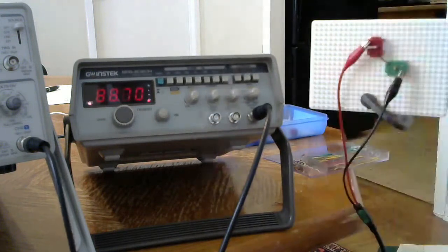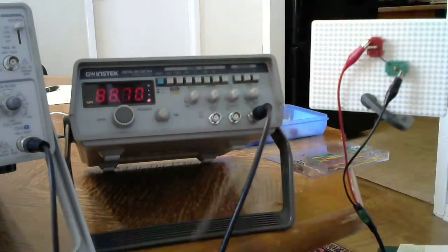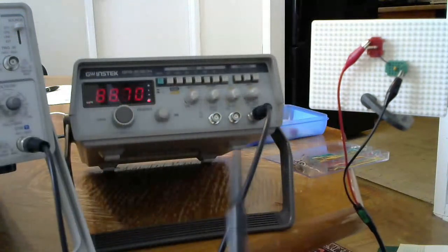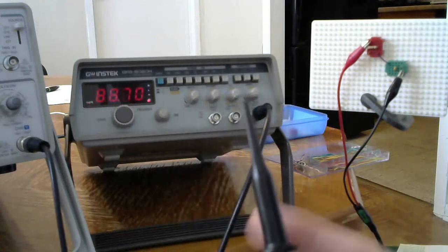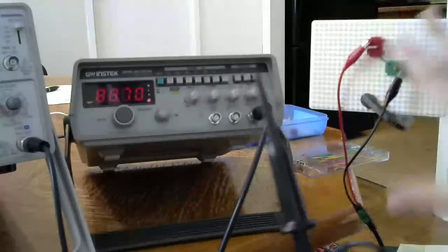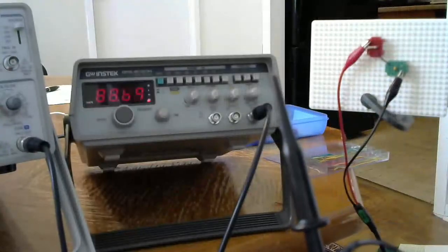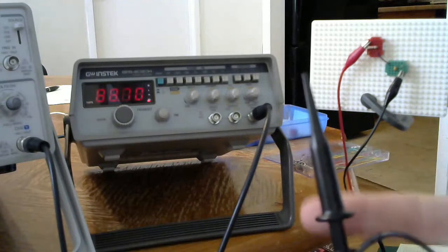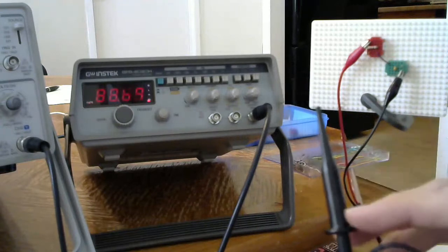So this is my channel 1 probe. And notice, by the way, that I've set this to 1x. This is a special probe that ensures that the oscilloscope doesn't become part of the circuit. It stays basically isolated from the circuit. There's capacitance and resistance in here that make sure that's the case.